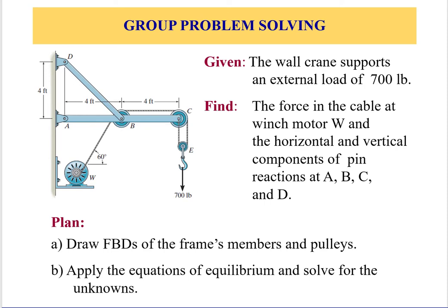As you know, the only frame structure we have here is AC. So this is a frame structure. The truss member is DE or DB, so we know its direction. It's going to be pulling, or tension. However, more forces will show up on AC.